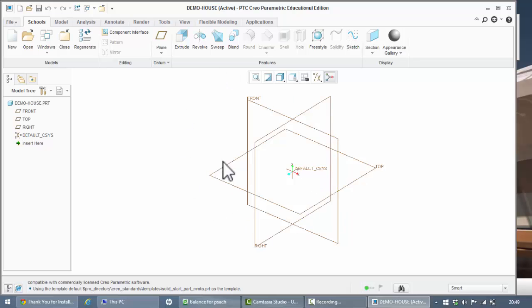So this is where we're going to create our house shape. The house is going to be roughly 90 long, 40 wide and 90 high. Okay. To do that, we need to make a drawing, like a plan drawing, of how long and wide the house is, and we'll then extrude that profile into 3D to give it the height. So the tool we need is an extrude.